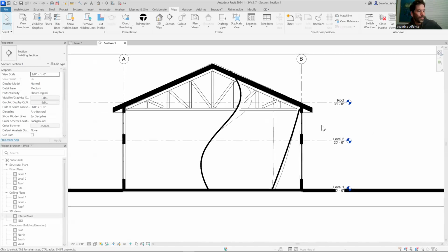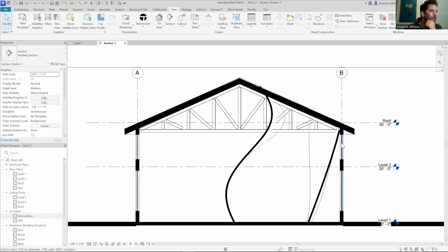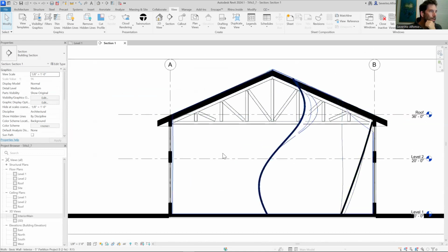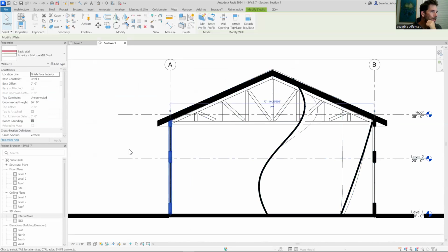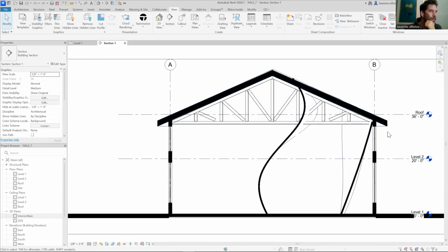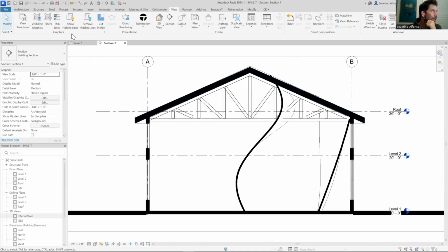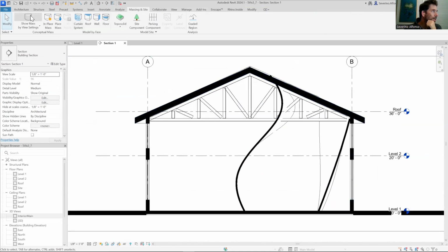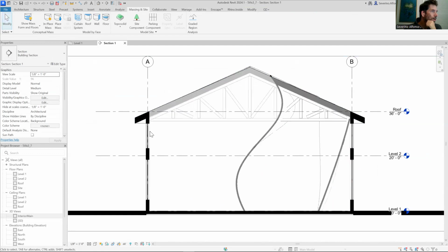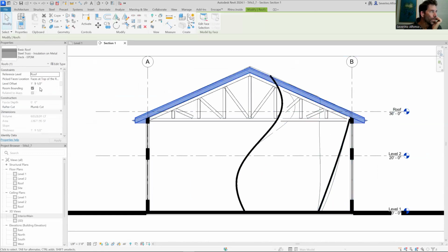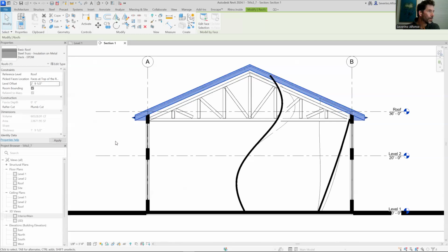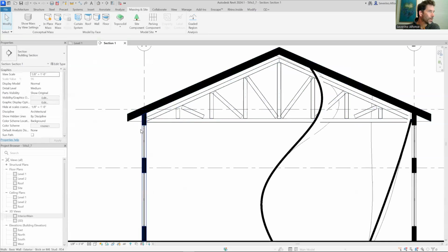Okay. Second video. Let's fix this issue with the roof here, which I can see that the interior space is not related properly to the roof. We can see that under massing inside and turn on the mass, and notice how it comes up to the top. We have to kind of invert the offset. So let's turn off the mass, select the roof, and I think it's just like a 2 feet offset to the top. So that should do it.